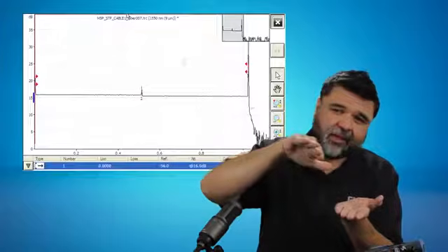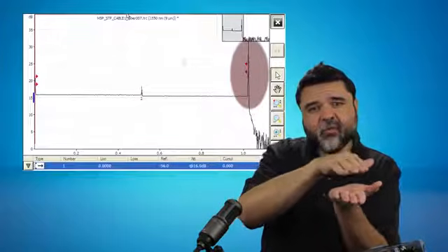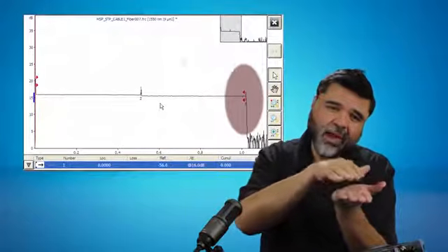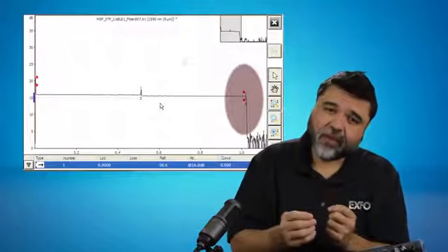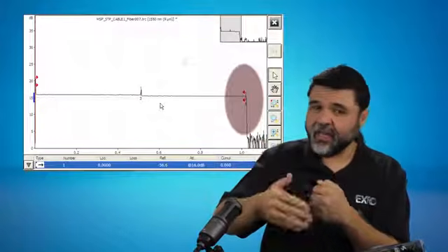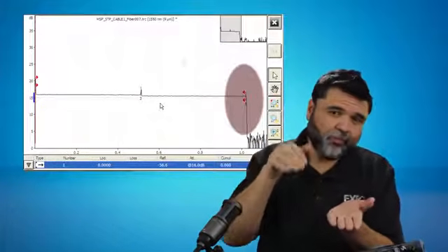And so anybody who's ever done any OTDR troubleshooting, if you crush a fiber, say mid-span with a backhoe or something, and you shoot an OTDR trace, you expect to normally see a spike if you have a termination panel on the far end. If it rounded off, so when I was a splicer, if I saw the fiber round off, that was an indication to me that I might have an open. And so when you crush a fiber, what do you do? You shatter the end face. So just picture that same tennis ball bouncing off of the cladding, hitting that rock wall, and just reflecting in a million different directions. And so that's one reason why you would see it round off on a damaged connector or a damaged fiber.